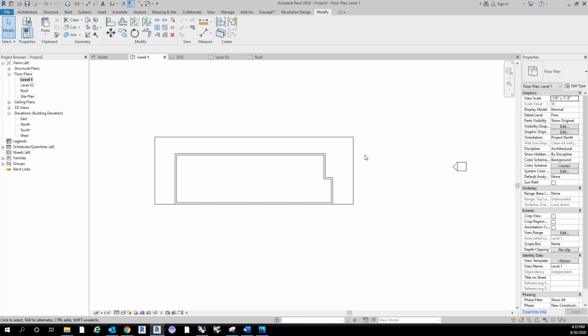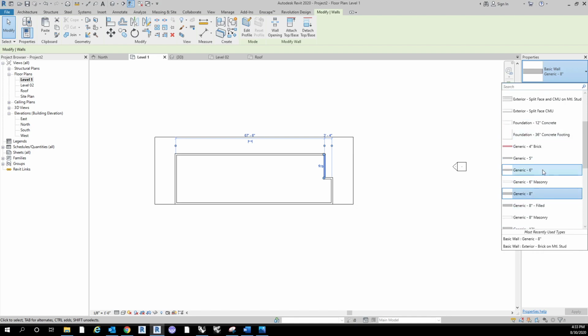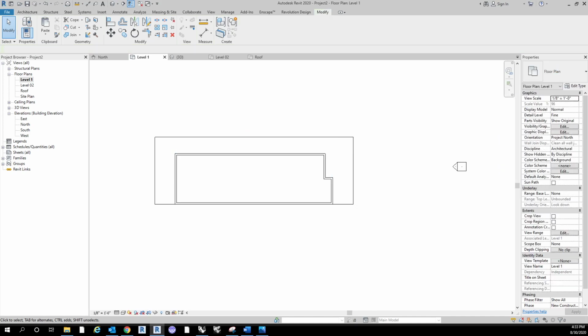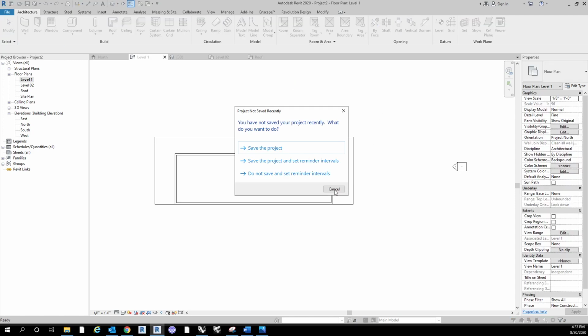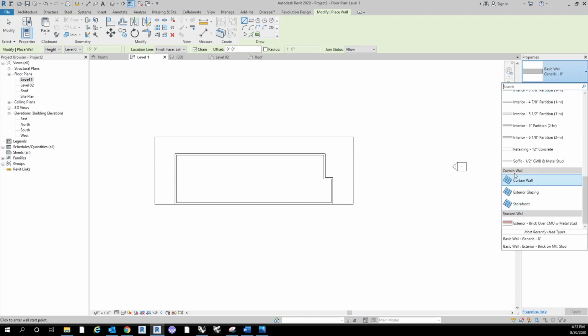All right, so right now we've just created basic walls, and basic walls are all these different types, and we can edit the structure of them, edit the materials of them if we so choose. But there's another type of wall, and that is the curtain wall family. In the curtain wall family, it's under the walls. If you do go to the drop down of the type and you go all the way down, it's distinguished here. And we can do one of two things.